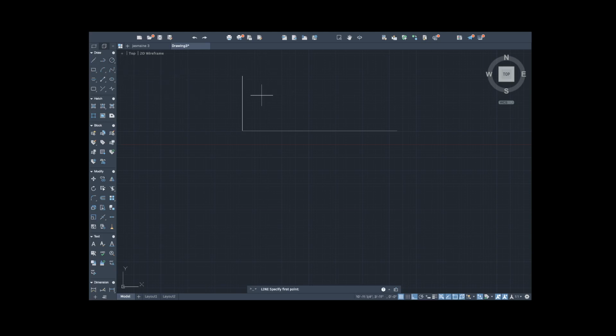We're gonna copy this line. So click on the line, press C, and it says specify the center. Sorry. Click on the line, type copy, and it says specify the base point. You can specify there, and then we shift it to this point, to the end point. Alright.